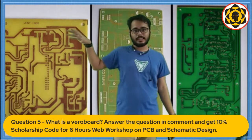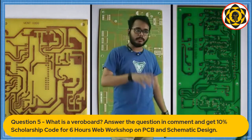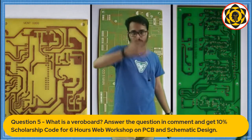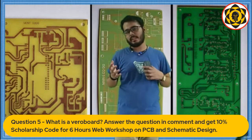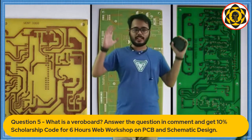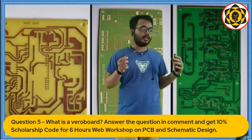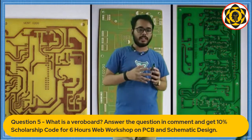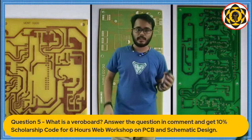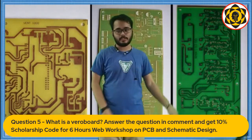One more thing, for simplicity, we'll be building a single layer PCB. It will have only one copper layer, one silk screen, and one set of soldering holes, on one side only. A multi-layer PCB is a little bit complicated, and you cannot really make it at home. It involves sticking 2 PCB layers together. It's very complicated. It works on a micron level, and you cannot do stuff on a micron level by hand, right? You need laser cutters and advanced stuff. So we're going to be making simple single-layer PCBs here.